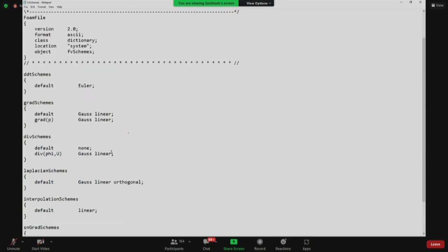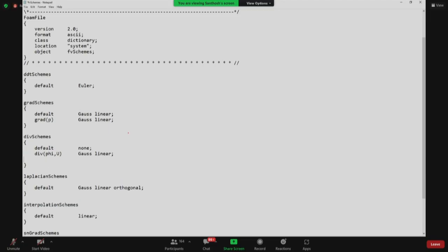So what I need is, I have defined a divergence term for temperature. So for that, I need to copy this. I have this divergence term in my equation. So for that, it is this. And let's say my divergence scheme for temperature will be upwind. Okay.